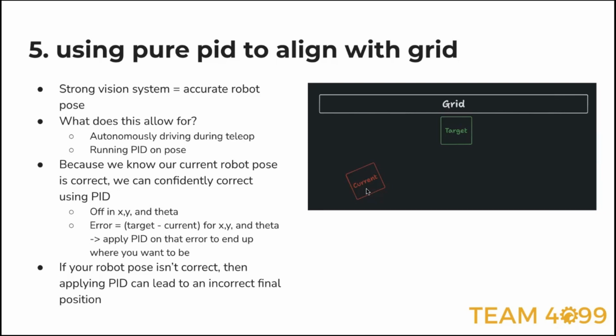So you can just use, I think, the swerve drive class within WPILib where you can just pass in a controller for X, Y, and Z, and then it'll give certain states for your swerve modules that you can drive to. And you can tune your PID constants in order to drive these positions.